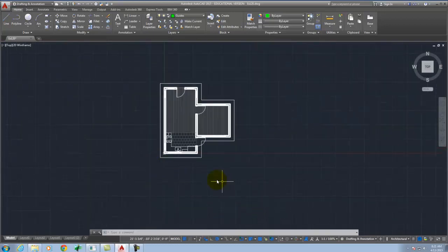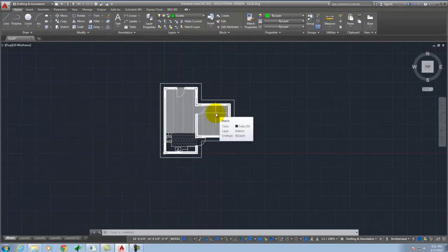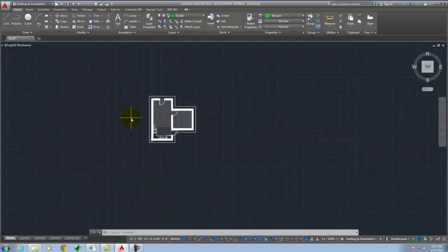I'm going to draw the south elevation directly below my drawing. Right? And the people that have taken 130 have spent a little bit more time dealing with this, but there are some drawing conventions that will help us to draw these things. One is that if we draw the south elevation directly below, we can use a lot of the floor plan to pull lines down to reference. Okay? And so that's what I'm going to teach you how to do.